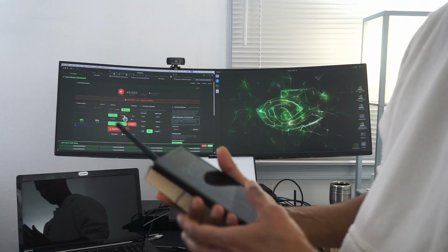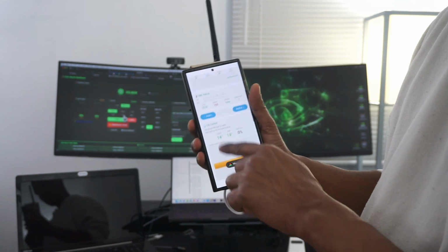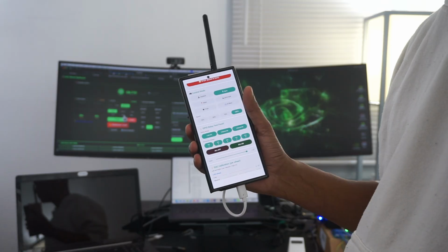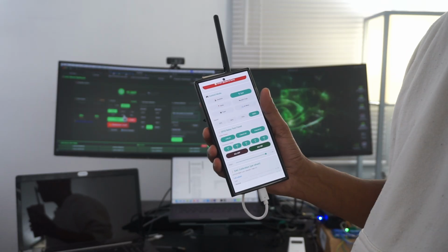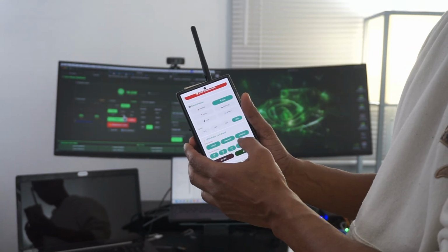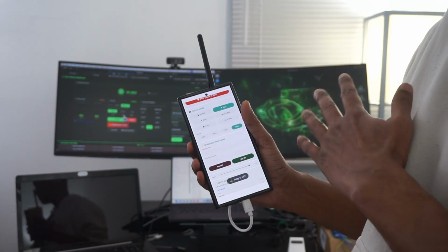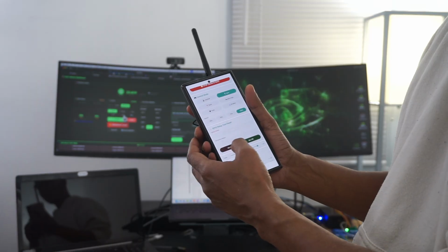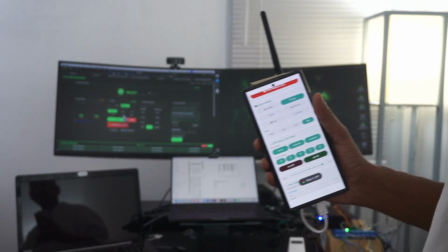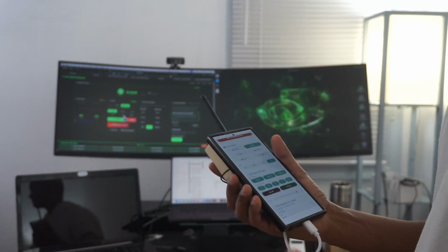And also, start. So it started. And then I can literally control all 8 relays if I need to turn off the seat switch or the neutral switch, or I need to bypass the controls. So literally all the switches are off at this point. So I can control all those things from my test panel, and then I can turn all of them on and off. But that way I have complete control over the lawnmower while it is in the field.